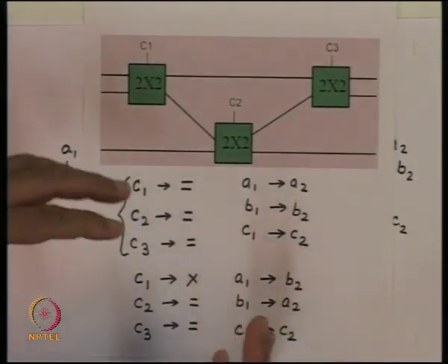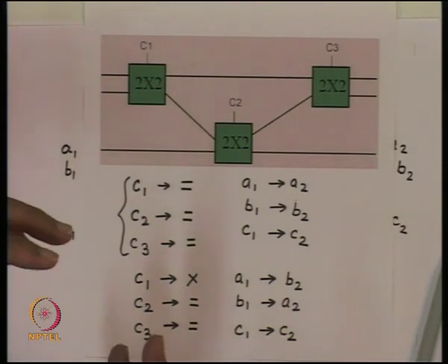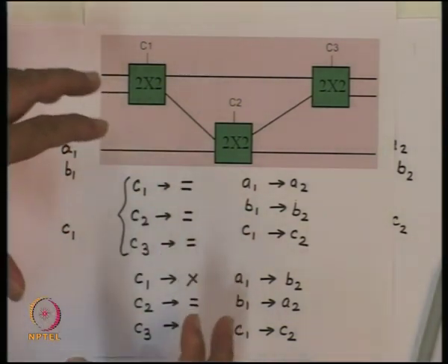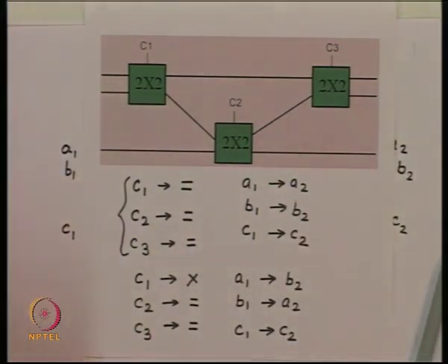So now see, by doing this complex architecture which we are developing now, we can have n by n switch created by using this basic device, whereby appropriate control signals, any of the input can be connected to any of the outputs. And by proper number of these 2 by 2 directional couplers, you can essentially create a non-blocking switch. And the optical signals can be routed and switched by using appropriate control signals to this device.